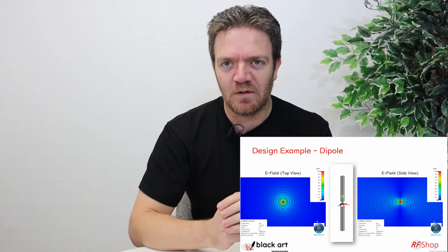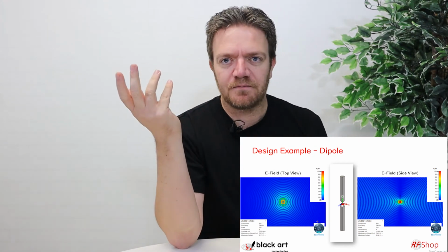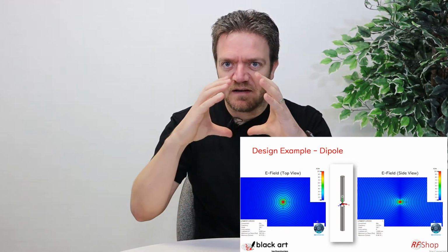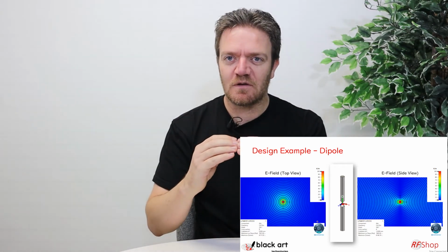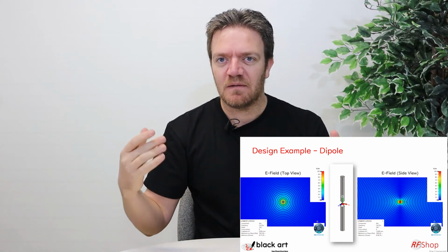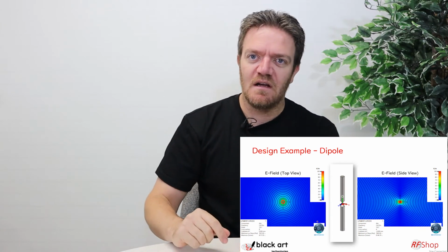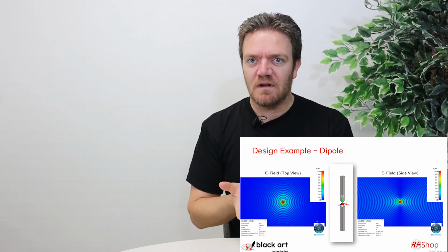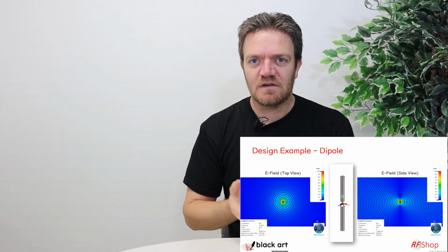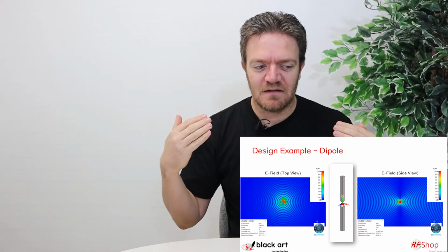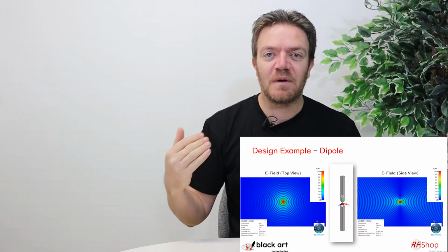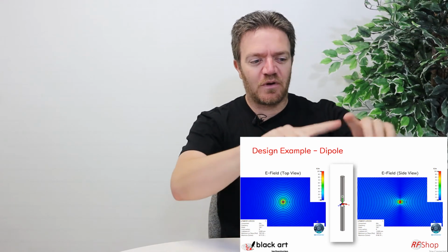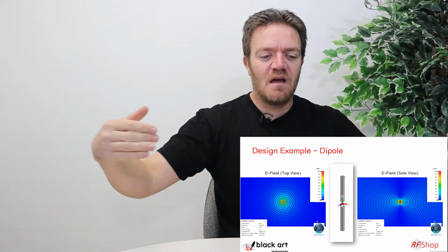want to call it a ring for lack of a better word, is say it's 1 watt. So there's 1 watt at the beginning. Then a bit later, it's 1 watt, but it's spread over a much bigger circle. Then a second later, it's much faster, but just for argument's sake, a second later, it is over this area. So this whole circle has to have the same amount of energy. So that's where path loss is significant, that's kind of the biggest contributor to what we consider path loss, is that same energy suddenly has to be spread over further and further areas.